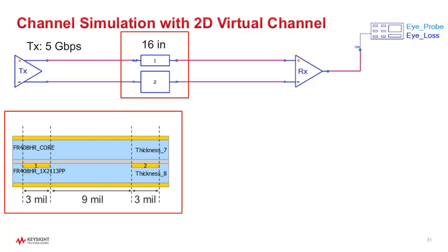Now we saw in the demo that the substrate height is 3.5 mils, and I know to multiply by 2, that's 7, and that gives me 46 ohms of single-ended impedance, and that is powerful. Within 5 seconds, I know what to expect. See, 5 ohms out of 50 without any major work. That is very astounding. You can use that rule of thumb everywhere, and it's very easy to use.